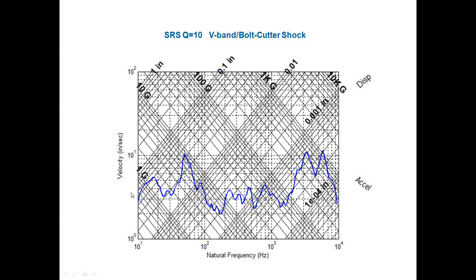Another thing to look at is that certainly the pseudo-velocity varies with natural frequency, that's clear. But the dynamic range, the ratio between the maximum peak and the minimum level, we could call that the dynamic range and maybe represent that in terms of dB. In many cases, certainly not in all cases, the dynamic range of the pseudo-velocity is less than the dynamic range of acceleration.